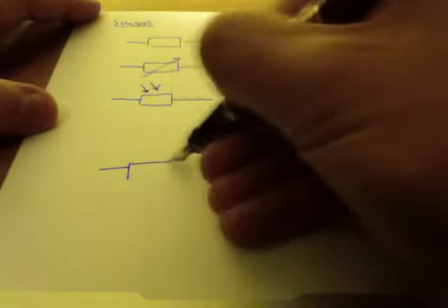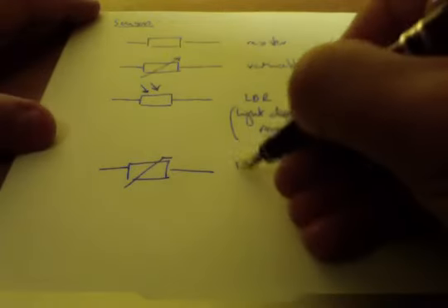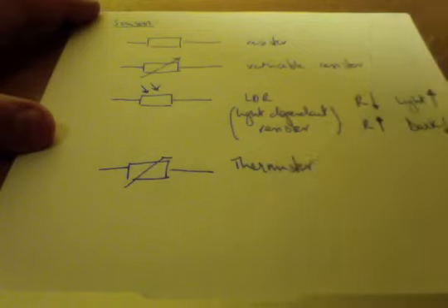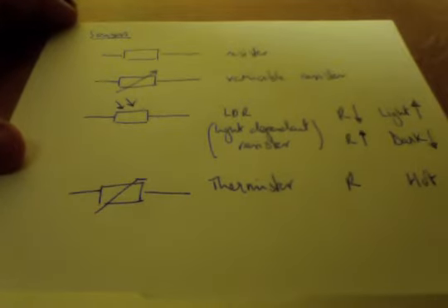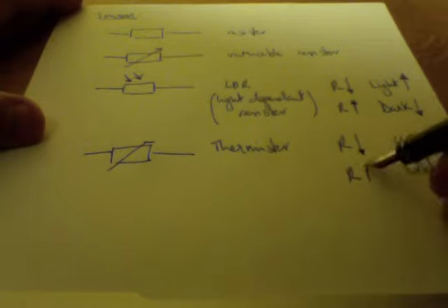What about this object here? The one I described as like a hockey stick. It's actually a thermistor. It behaves differently with temperature. So let's imagine this became hot, i.e. the temperature has gone up, the resistance goes down. If it becomes cold, well, the temperature is coming down, the resistance in actual fact goes up.